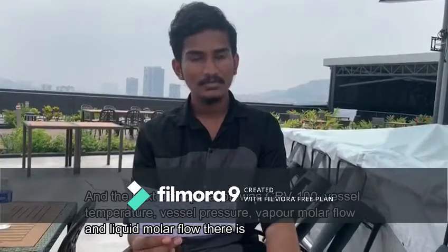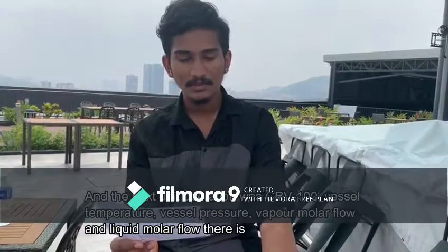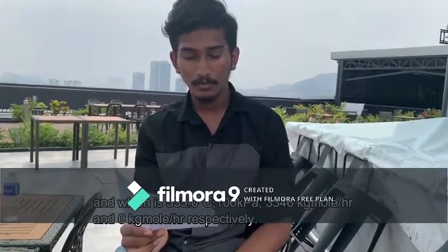And the next unit operation was CRV 100, with vessel temperature, vessel pressure, vapor molar flow and liquid molar flow, which are 535 degrees Celsius, 100 kPa, 3346 kilogram mole per hour and 0 kilogram mole per hour respectively.